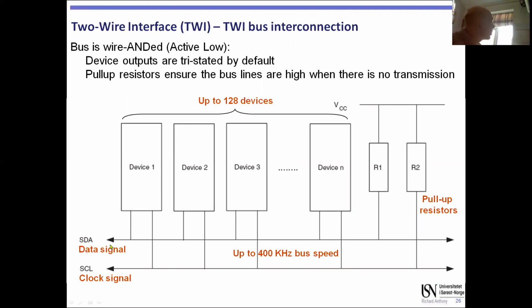You just connect all the data signal together to every device, your Atmel and all your sensors, and maybe there are 2 Atmels, 3 Atmels, and 10 sensors. By the way, this is an interesting idea, right? Supposing you've got 1 temperature sensor and 3 Atmels, you could do this.